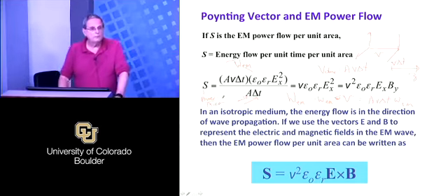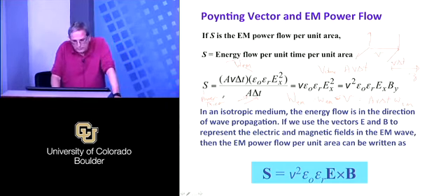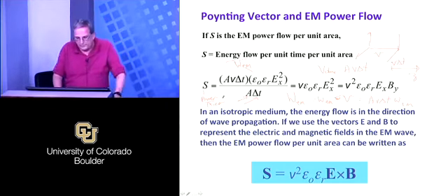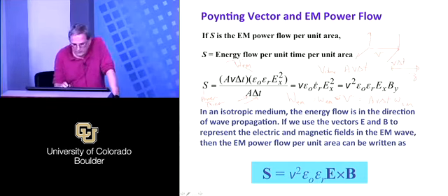Okay, so the Poynting vector is in units of power per area. For that plane wave, then it becomes this V epsilon E_x squared. We can write it in terms of that, or more in general, it becomes this over here. Okay, so that is the Poynting vector, something like V squared epsilon naught epsilon_r times that.